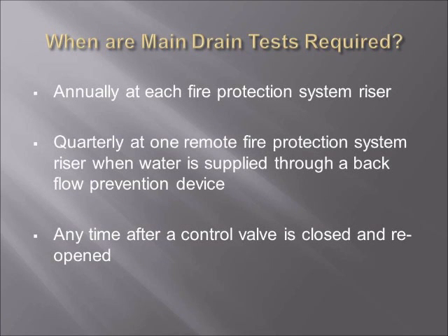When are main drain tests required? NFPA 25, the standard for inspection, testing, maintenance of water-based fire protection systems, the 2002 edition, as referenced by the Indiana Fire Code, mandates that a main drain test be performed annually at each fire protection system riser.